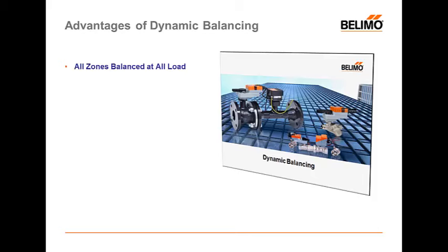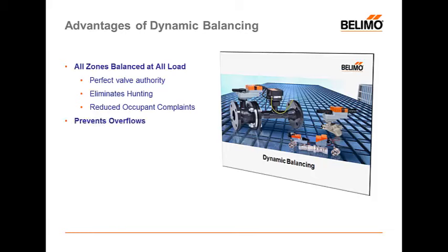There are several benefits to using dynamically balanced systems. The number one benefit, obviously, is that all zones are balanced at all loads. We have perfect valve authority, and this will eliminate the hunting for your set point, and it should reduce the occupant complaints for discomfort. In addition to that, we're going to prevent overflows. And anytime we can prevent overflows, we can improve the delta T at our coil and potentially lower our costs for pumping water. And we never need to rebalance these devices.